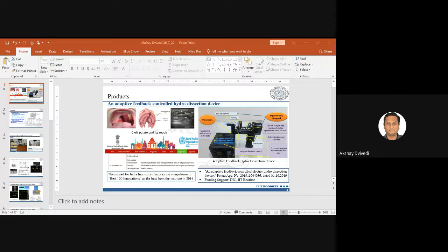The idea in this process is that hydrogen will be evolved at this tool, which is given a negative polarity. And over a period of time, as you go on continuously increasing the voltage, the tool will be enveloped by hydrogen bubbles, and those hydrogen bubbles will create a sort of insulating film over the tool.